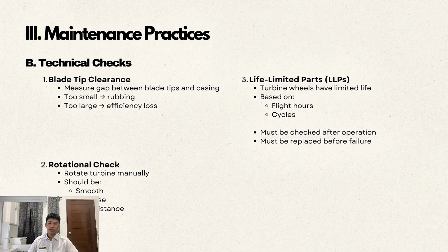According to engine servicing procedures, only specified consumable materials, lubricants, and hardware must be used. Correct torque values must be applied during installation of components. Proper procedures for lock nut installation, fittings, and tube connections must be followed. Components must undergo inspection and be checked to determine serviceability. The manual also indicates that parts showing wear, damage, or corrosion must be replaced. Maintenance must follow the prescribed inspection and troubleshooting procedures.